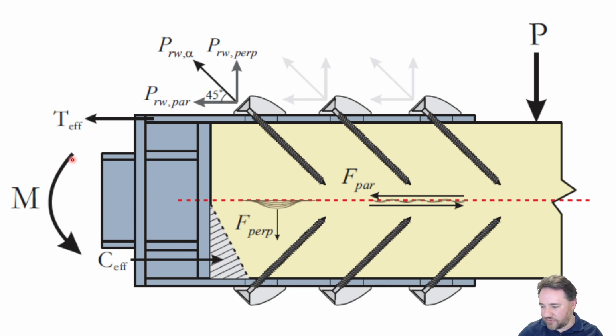I wanted to show you an example from our own work at the university. This is from some research that we did a number of years ago, looking at connecting steel moment yielding connections to timber beams. And one thing that you can do with these self-tapping screws is if you install them on an angle, you can really increase the lateral resistance and stiffness by quite a bit. Because now you're engaging it not only in shear, but in shear and in tension simultaneously. And these have a really good withdrawal resistance because of the spiral on the shank.